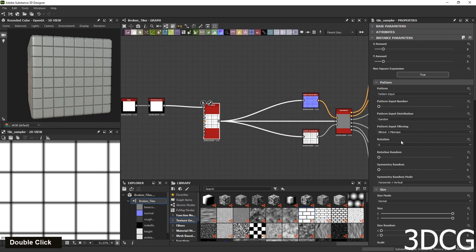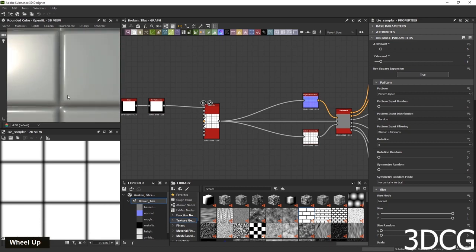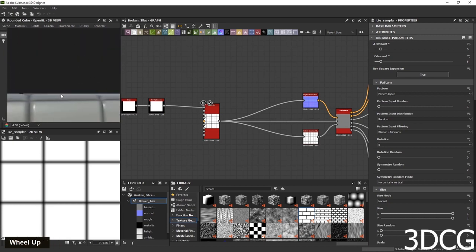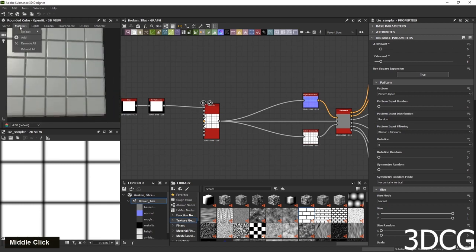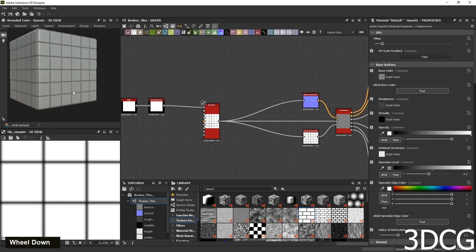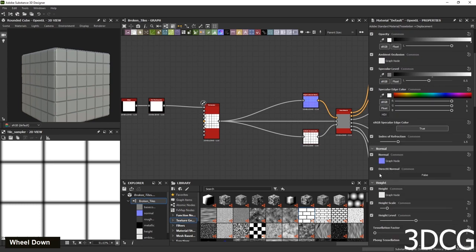The 8 by 8 is a little bit too much. So let's change that to 6 by 6. Yeah, it's a little bit better. All right. If you're not seeing the height, actual height and displacement like so, quickly go to your 3D view, material, default, edit. In here, you have control over your material that you're seeing inside 3D view. So tiling and other good stuff. Here, DirectX normal, by default it's false because we changed that into a setting.